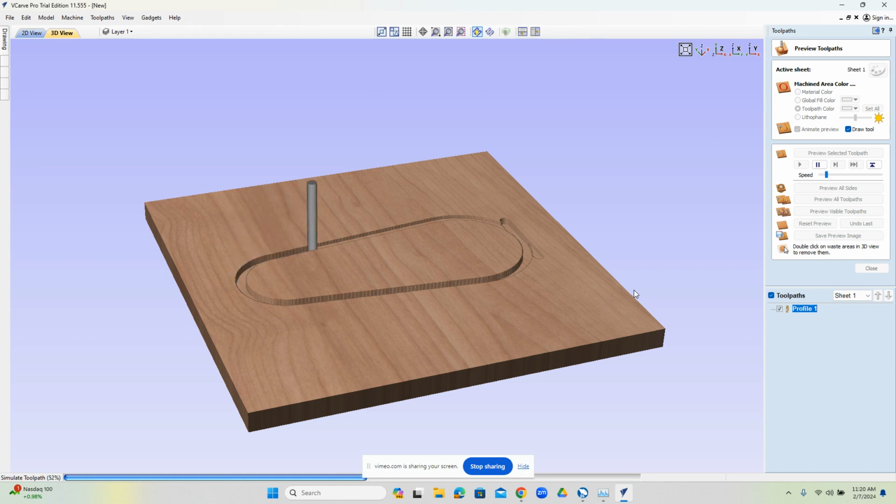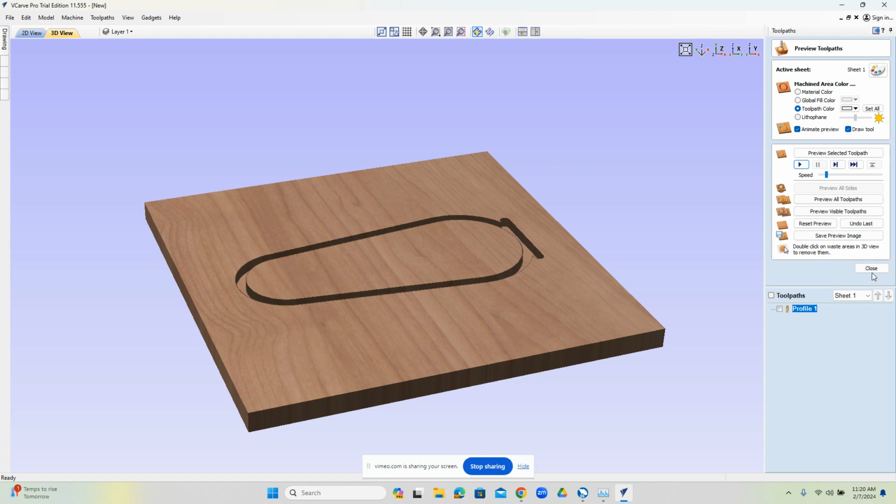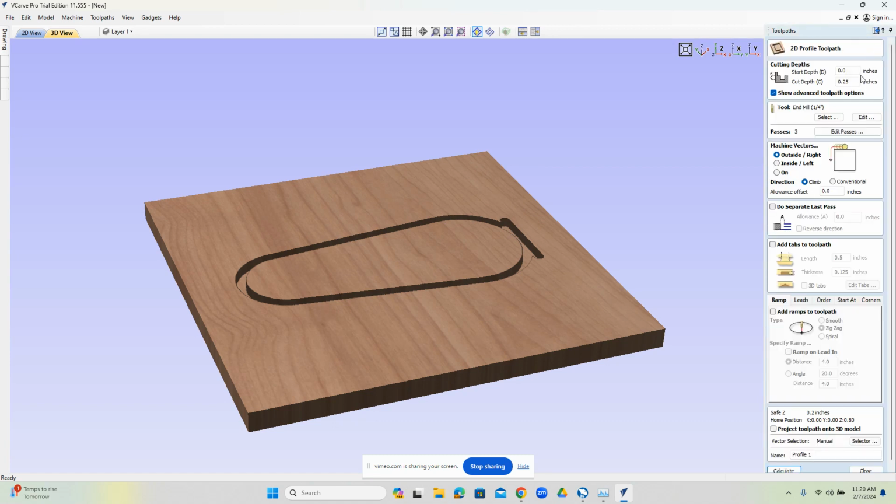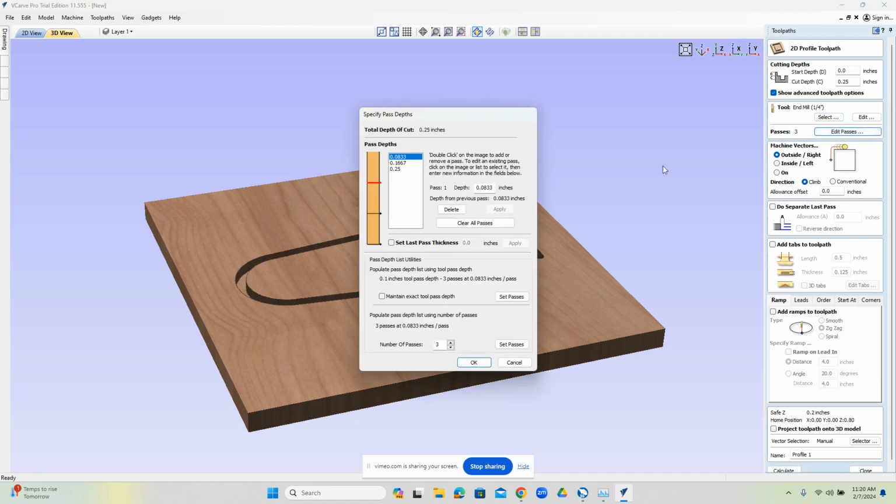What I normally recommend for the finishes, some of these smaller machines, they leave a bunch of lines that came up in another group, and you're trying to get a nice consistent finish. That could happen for a number of different reasons. So what I kind of like to do is have a rough and finish. So if we come back in here, okay, so in Vectric, you have your depth of cut, but how much it increments is based on your tool setting. If we edit our number here, another thing you could do to eliminate the burn is maybe reduce your